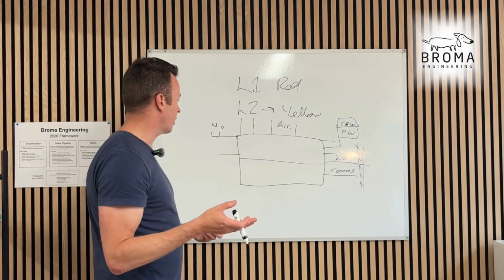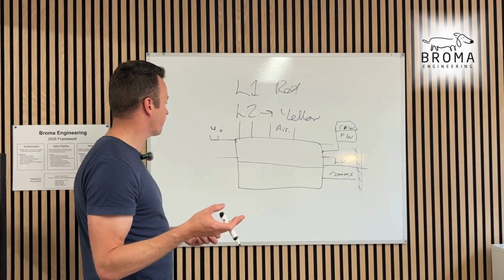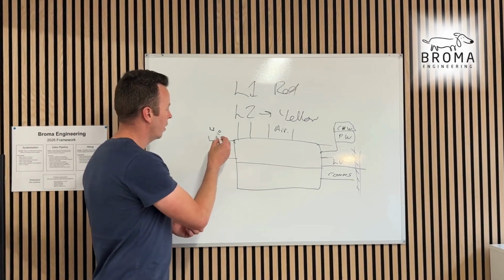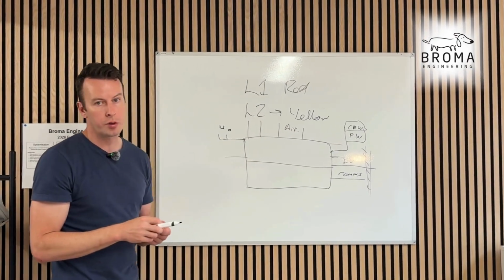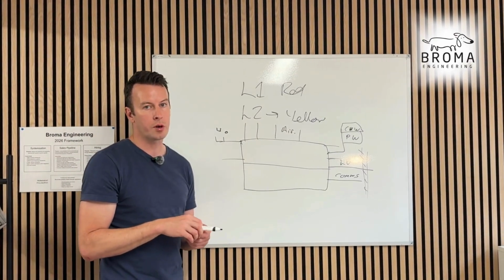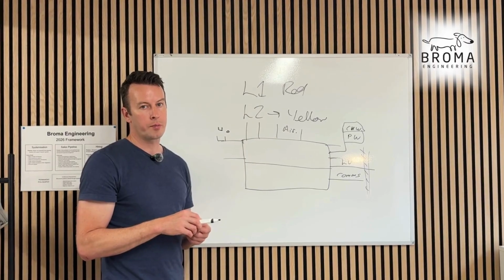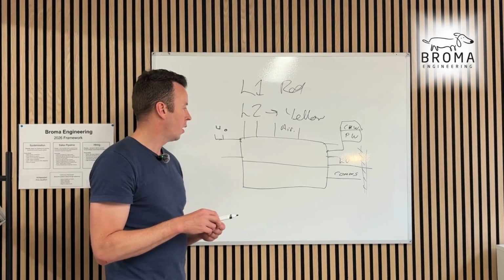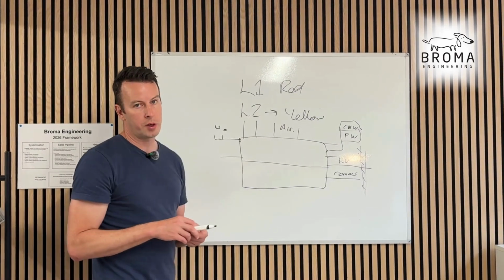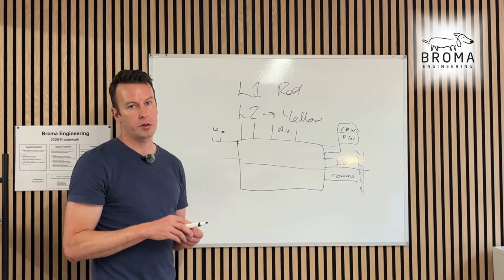If there's a number of phases going on in one stage at one time, we should know what's going on as well. And maybe you can put some pipework in, maybe you can put some containment in, maybe you can pull some cables, but it needs to be accounted for, and you need to know what you're doing. I would say get as much in as possible before they arrive, but don't be taking stuff down on the day because there's a clash.